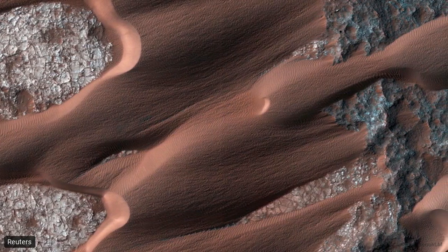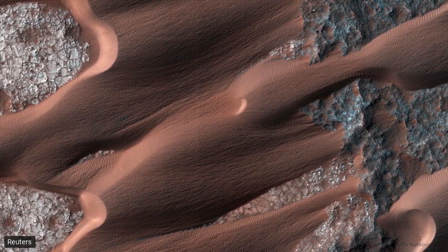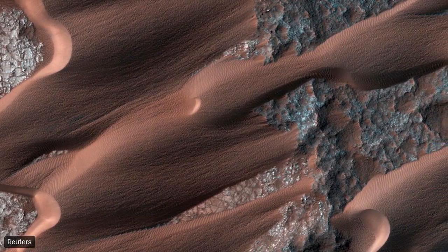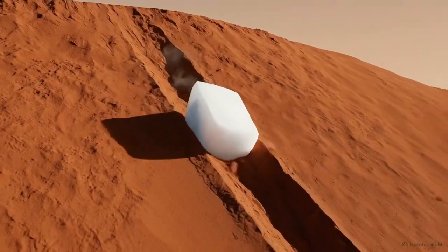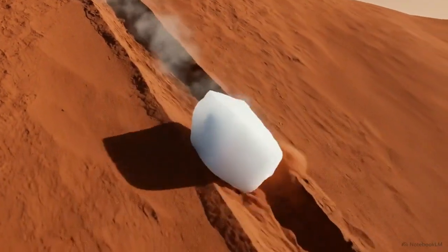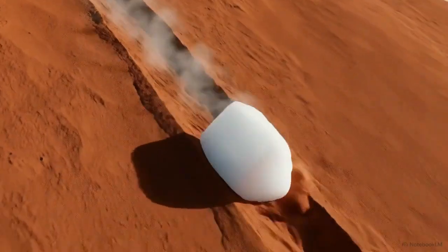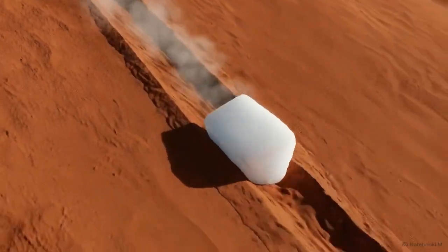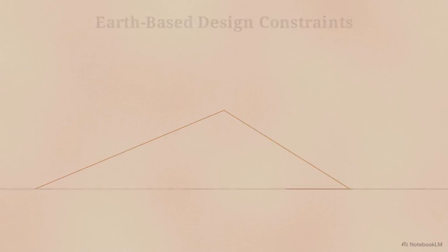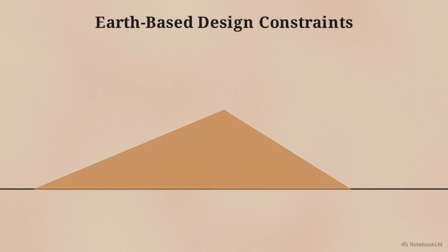To map the precise slopes required for a stable sand architecture on Earth, we look to the extreme physics of Martian dune fields. Experiments replicating Mars observed a distinct regime change. When solid blocks of dry ice interact with slopes below 22.5 degrees, they safely burrow channels. But hit 25 degrees, and the blocks begin an uncontrolled, damaging slide. We translate those planetary mechanics directly into strict geometric boundaries for our Earth-based design.